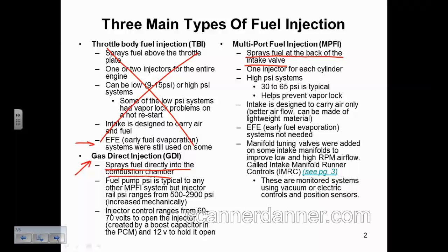What's going to differ would be rail pressure tests and determining fuel rail pressure with this step up in pressure. They're using a hydraulic mechanism to do it. They're pumping that 100 psi pressure into a mechanical fuel pump that's raising it up to the needed 3,000 psi number.